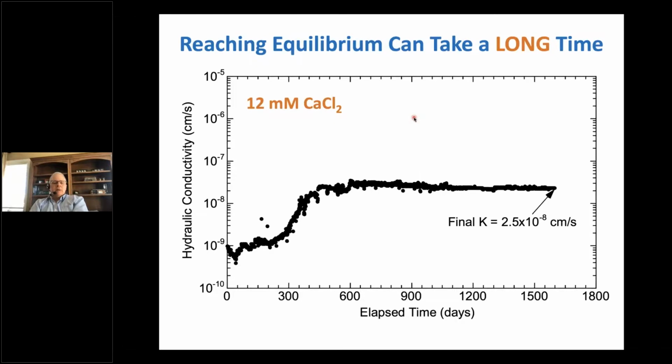I've got a couple more slides. I've shown all those other slides in the context of pore volumes of flow, which really doesn't convey time, but time is important. These tests can take a long time to run, and I show this graph as hydraulic conductivity versus time. We see it starts off low, and this is a dilute solution, so it's got a very slow change over time. And to get to equilibrium, this one's almost 2 years.